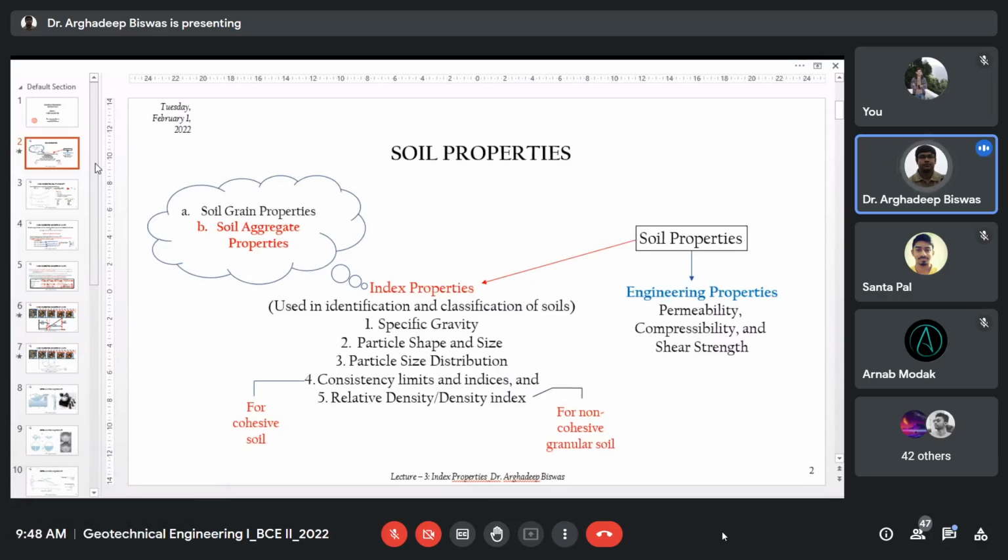So these are the particle size ranges. Of course, please remember this size is equivalent diameter. What is equivalent diameter? Just suppose we have a cube and a spheroid like a marble. With the volume that the cube has, if you prepare a sphere, the diameter of that sphere will be called the equivalent diameter of that cube. So for any shape, any size, you consider the volume represented by an equivalent spheroid, and the corresponding diameter of that spheroid will be called the equivalent diameter.